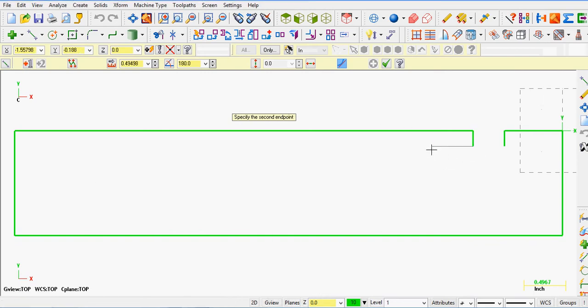I'll give it the direction, click, come back up here to the length, and enter my equation, which was 0.625 minus 0.375. Press enter, I'll have my answer, and now I can take the 1/4 inch, click twice, add the divide sign by 2, enter again, and now I have the proper line length. So once again, I can select this as the endpoint for the next line, or I can come over here, give it the sense of direction, and re-enter 0.125 as the length. If I'm happy, I can choose Apply. Okay. So we're almost done.